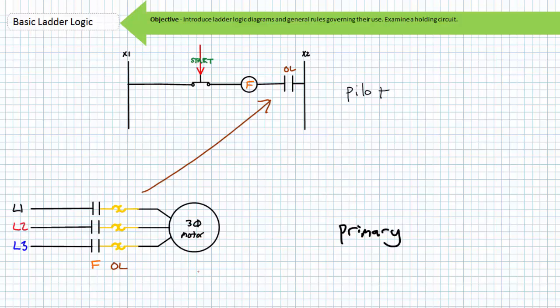This is totally cool. The ladder logic diagram illustrates this function in a single line. The only way you can turn this motor on is if you're pressing the start push button and the overloads aren't overheated. Which begs the question, how do you turn on a motor or extend a cylinder at the touch of a button? I don't know about you, but standing around holding down a momentary normally open push button all day to run a stupid fan or dumb pump isn't one of the things I consider a rewarding priority.